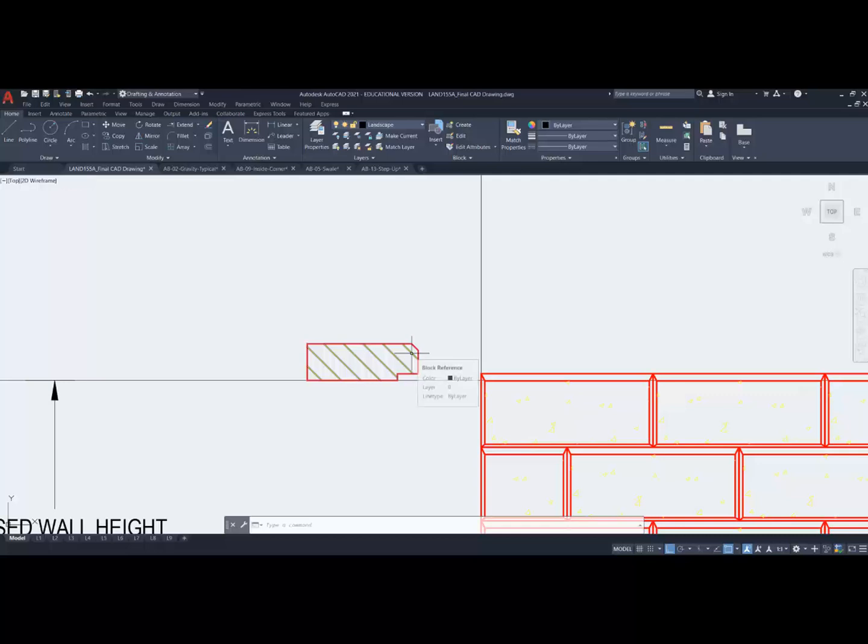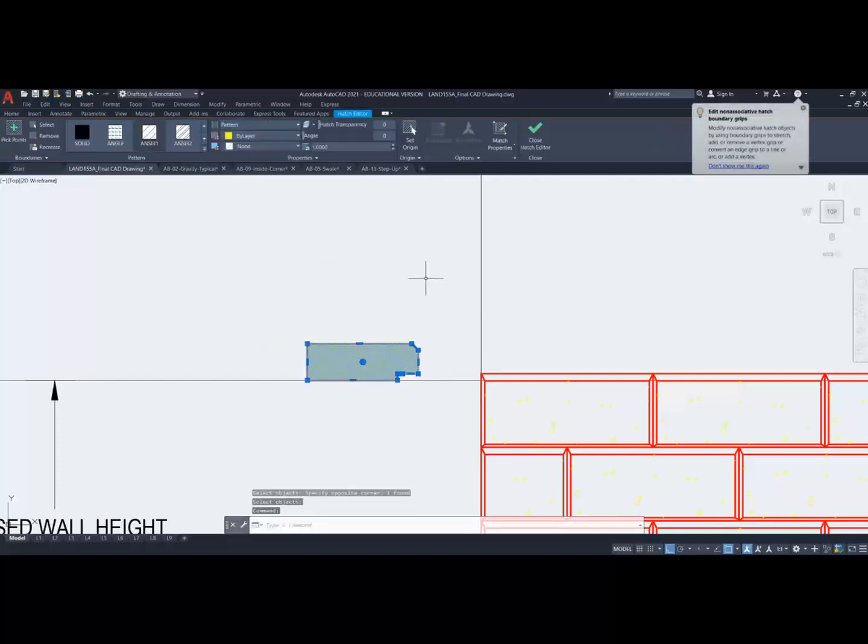So that notch is actually not seen, but that face is flush with this face. Okay, I don't want to hatch this because it's an elevation. So I'm going to, oops, remove that. They must have blocked all these elements together. So when I try to remove that, press delete, the whole thing went. I'm going to type in explode. You can see this command is really handy when you're using other people's works. And I can delete that.